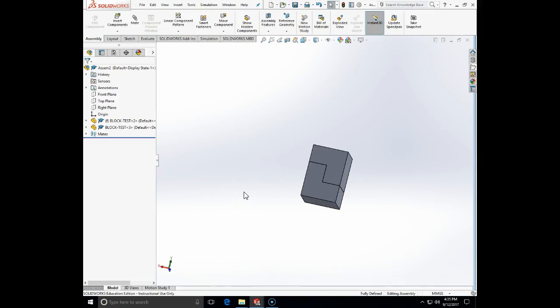That's like the assembly on page 309. So we made 3 different assemblies from the 2 simple parts. We can continue experimenting with any different possible combination of those 2 L-shaped blocks and practice the mates command. The first mate that we are practicing here is called the coincident mate. There are many other mates which we will explore today and in the next class. However, let's first get familiar with the simplest one, which just lets us glue the 2 surfaces.